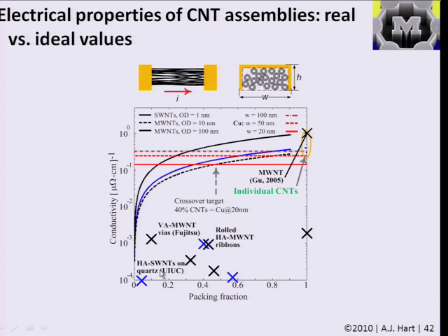And this is, in the end, meaning to compare the properties of individual carbon nanotubes to the characteristics of small copper wires for the application of electrical interconnects. And we can see that individual nanotubes have been measured to be as conductive or more conductive than copper wires of certain sizes. So if you have a short nanotube that's in the ballistic transport regime, you have a very, very good conductivity if that is a very high-quality nanotube. However, by and large, all different methods of making networks of nanotubes have failed to even get within 2 orders of magnitude of the bulk conductivity of metals.